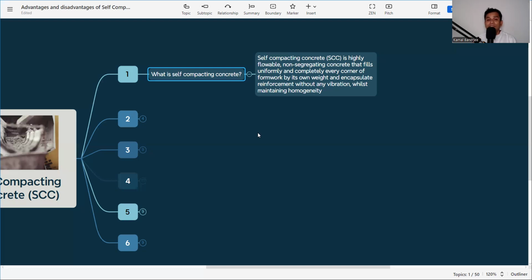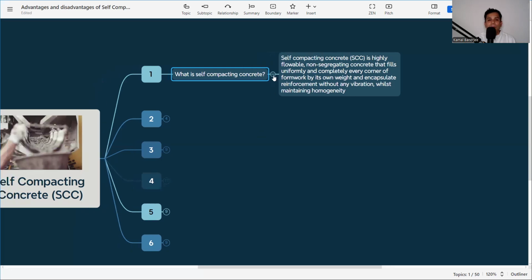So this self-compacting concrete or self-consolidating concrete, whatever, is very important now in the construction industry. It helps in many ways in congested places, in thin members where vibration is practically impossible, and for congested members where concrete reach is a problem. It solves that problem very diligently. A problem was solved so easily: if it is congested under the rebar, how will concrete go without vibration? Now the problem is solved. So that is called self-compacting concrete.